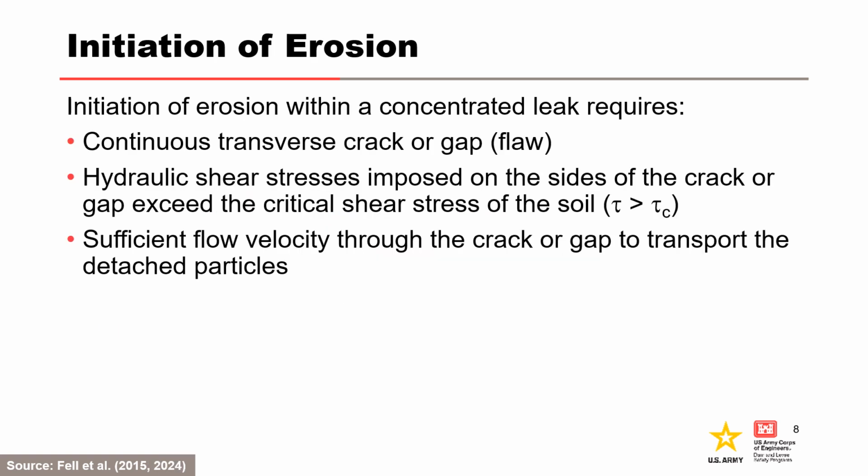For concentrated leak erosion to initiate, a continuous transverse crack or gap must exist, and the hydraulic shear stresses imposed on the sides of the crack by water flowing through the crack must be greater than the critical shear stress of the soil. The hydraulic shear stresses are dependent on the crack width and the gradient of the flow of water in the crack. The shear stresses are larger for wider cracks and larger gradients.